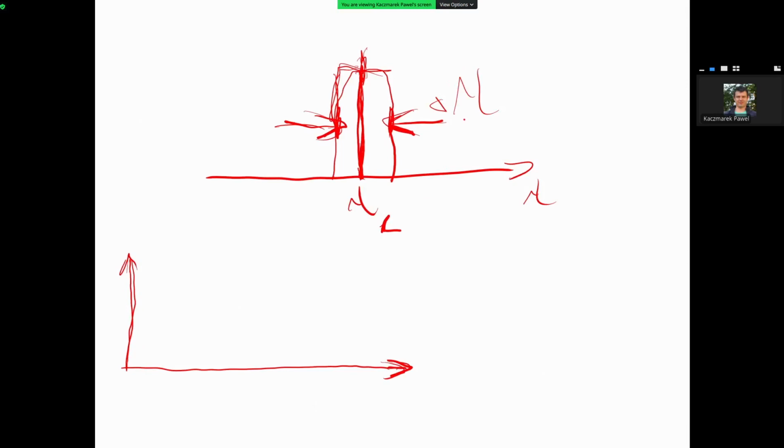If we are, for example, using AM modulation, AM meaning amplitude modulation, the principle is quite simple. If we are modulating with a signal which has some certain frequency range, the spectrum from 0, for example, to 1 gigahertz, so our modulating signal has such a range of frequencies, so we are modulating with a maximum frequency of 1 gigahertz. It means our carrier wavelength will also be broadened by exactly the same frequency.